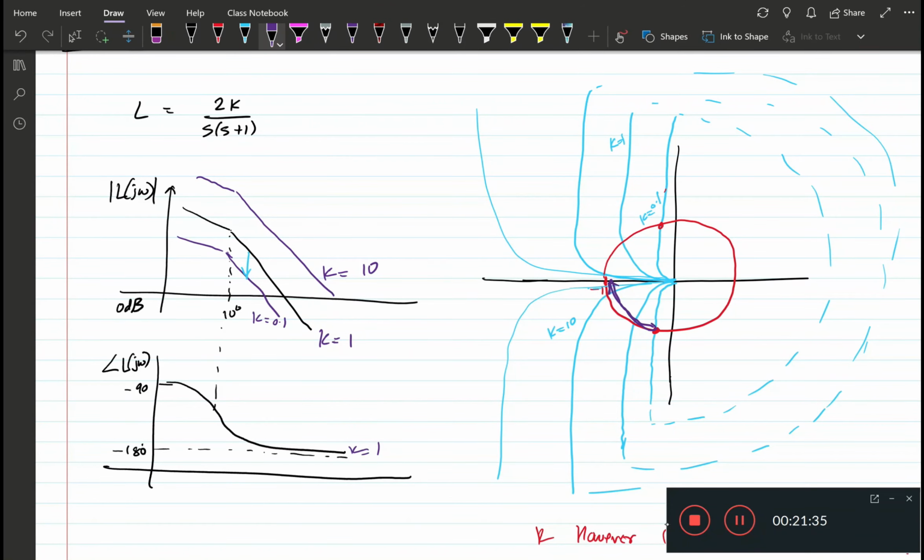This means you would have to rotate this by this angle in order to lose stability, and you can see that in the Bode magnitude plot by looking at the 0 dB line. This is the intersection, and this figure is not to scale, but that difference would be the phase margin, and the lower you make this, the sooner it will intersect the 0 dB line, and the higher the phase margin we would have.